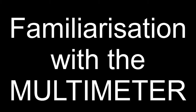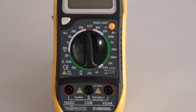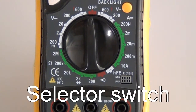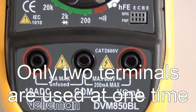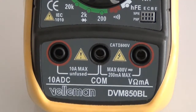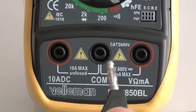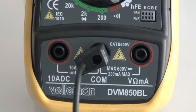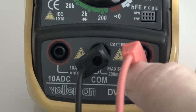In this short video, we shall familiarize with the use of a multimeter. The multimeter has a selector switch, and there are 3 terminals, 2 of which are always used at any one time. The center terminal is called the COM and is always used. COM is short for common. And in most cases we shall use the right hand side terminal, which is the volt, ohm, milliamp terminal.